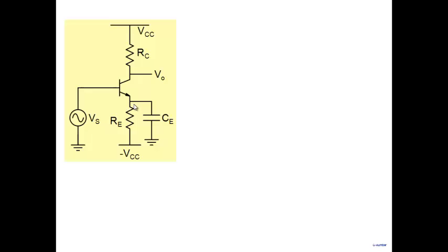You know that you don't actually get small signal ground. What you get is a CE, and what does it do? It provides a very low impedance. So let me reframe the question: under small signal condition, you're looking for a very low resistance at this particular point here. Low resistance, low impedance, whatever you call it. But whatever you connect here should not disturb your biasing. Biasing should still occur properly.